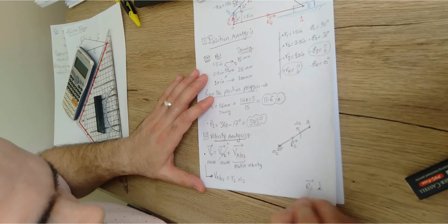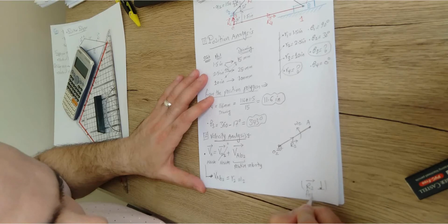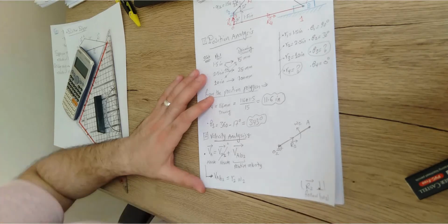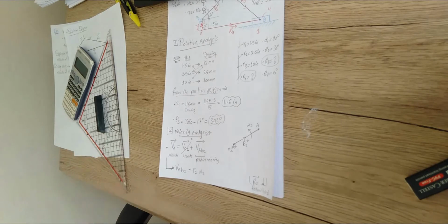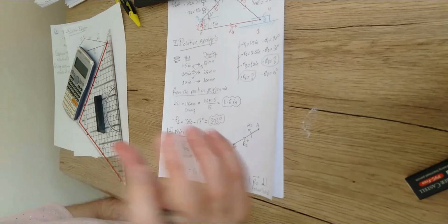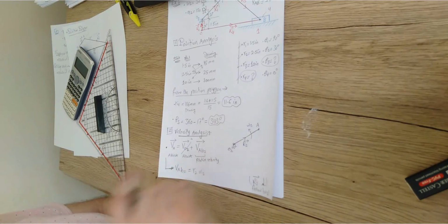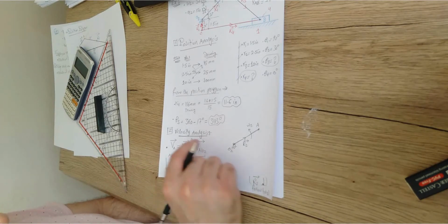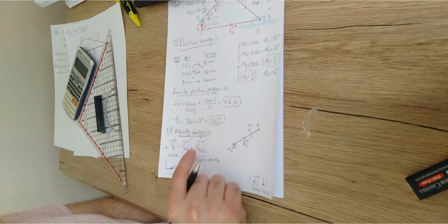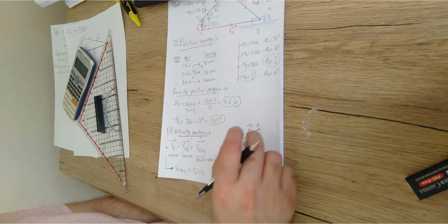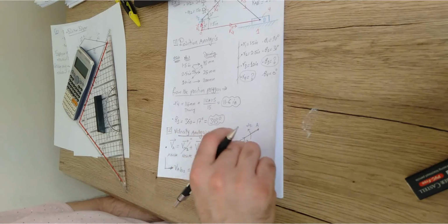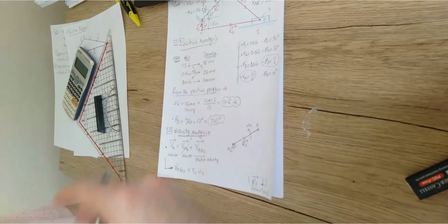Follow the direction of omega 2 as we did in the analytical analysis. The things that we mentioned in the analytical analysis, or the complex algebraic method, we're going to use here. But here you have to memorize these things. You have to remember that in case you have a link that rotates about a fixed point, its relative velocity is r omega 2. What is r? This is the r of the link. Omega is the angular velocity of the link, which would be given or unknown.